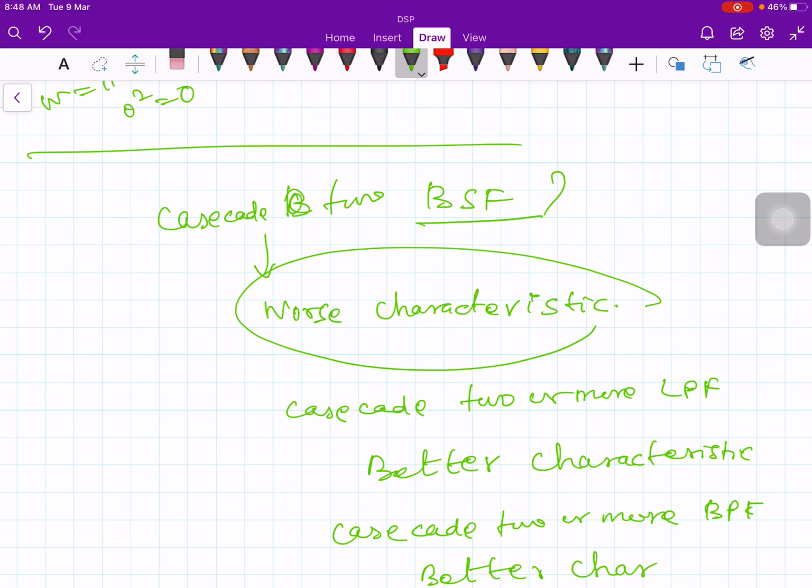Okay, and people, particularly in fields like biomedical signal processing, depend on such intuitions. There are people who will give you a filter. You will design a filter, and these are the basic blocks they will use. Generally they will use 1/2 (1 plus z inverse) for the low pass filter, 1/2 (1 minus z inverse) for the high pass filter, right?